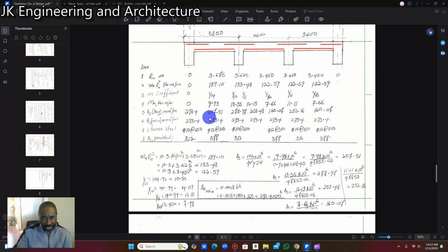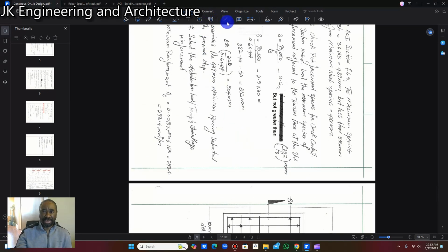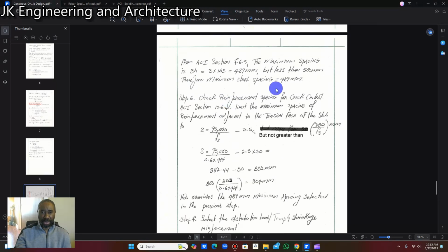So the requirement for this slab is going to be 3/8 bar. I could have reinforced this slab with only 3/8 bar and it would still be safe. But because I want to be on the conservative side, I reinforced all my tension bar here in the tension zone of the slab with 1/2 inch bar. All right, so I'm going to skip a few steps because some of the steps is not necessarily a requirement per se.